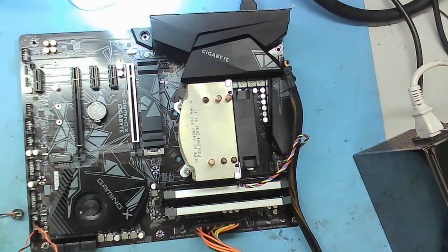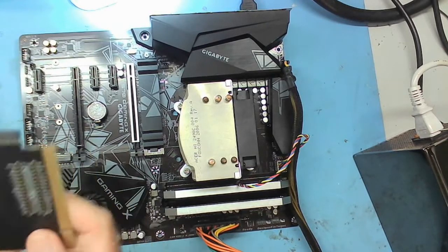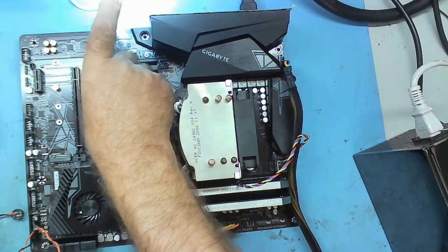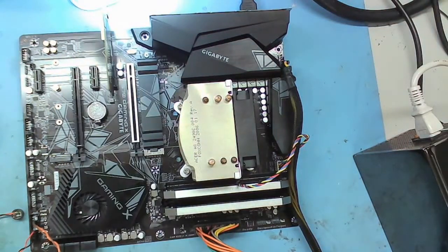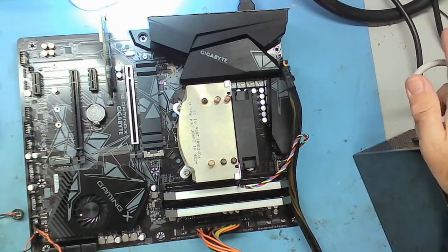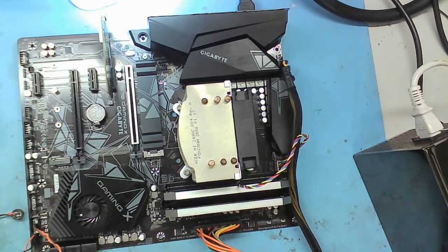Let's take our, who makes this thing? Gigabyte, yeah. Let's try to stick our post analyzer card in it, because it mentioned that Gigabyte actually used the PCI, if that's understanding the Chinese English manual. Well, that says I've got standby power. There's a little green LED on it. 0, 0.